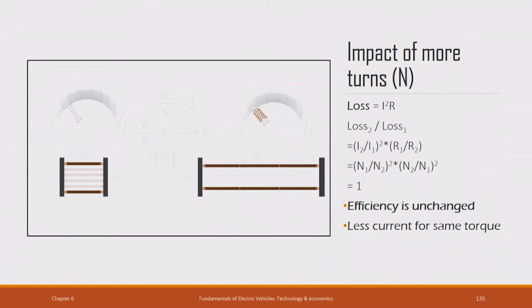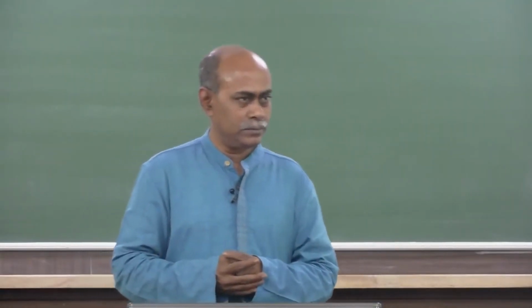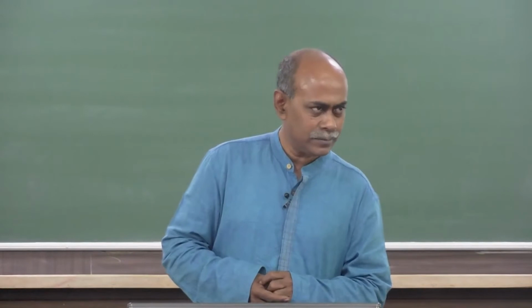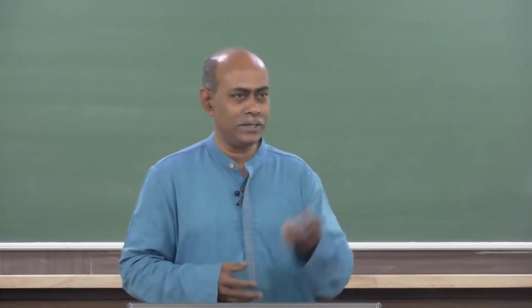But in the world, nothing comes for free. I am using the same number of conductors. Just by changing the way in which I wind, I have converted a low torque motor into a high torque motor. What is the price that I pay? There is no rupee price. I am not using more copper. Nothing I am doing. Somewhere I should lose something if I gain something. That is the law of nature. Yeah?